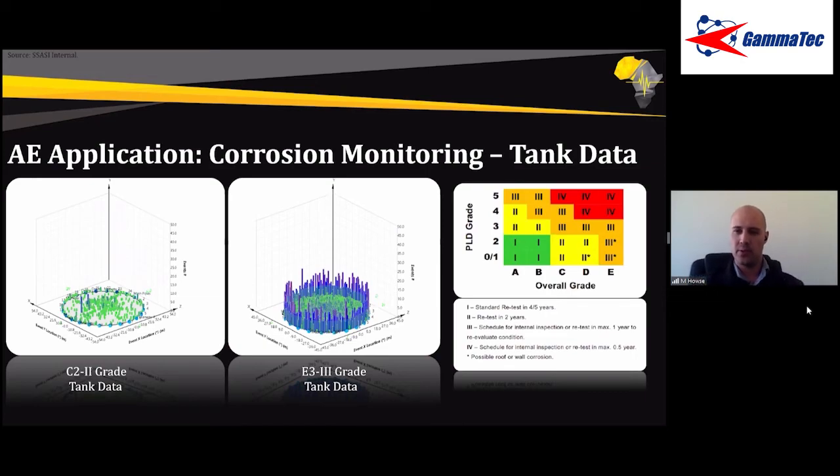So for the bridges, here we have, is it only applicable to long-term monitoring? It is best used with long-term monitoring. In general, the bridges that are monitored are the ones that we're concerned about because of the number of people that need to use it each day. So generally, you'd attach hundreds of sensors on these bridges and monitor it under traffic load.